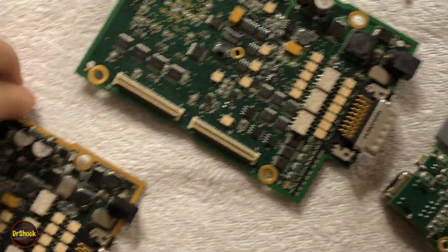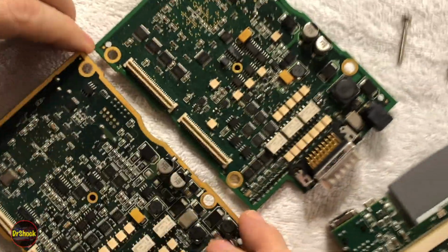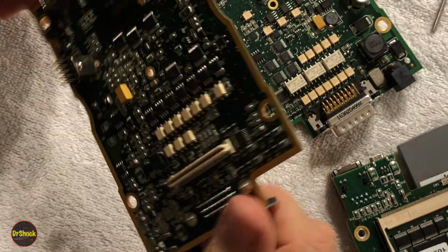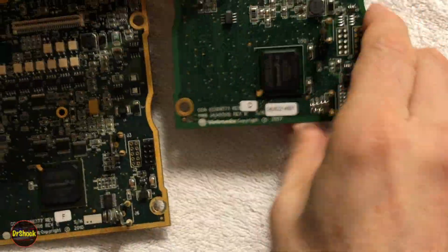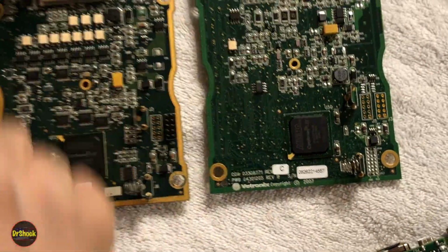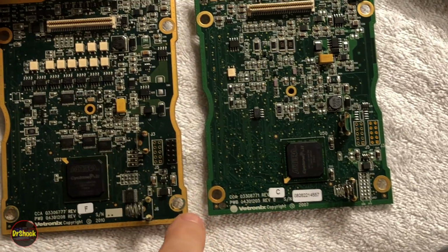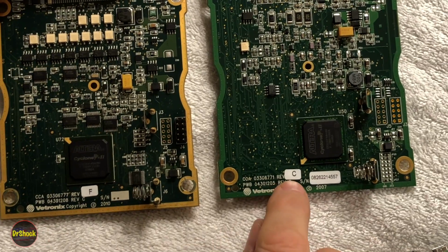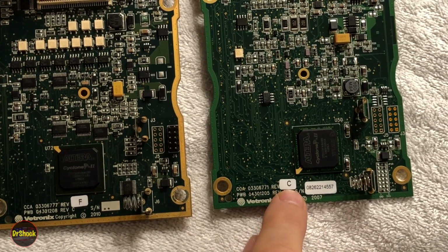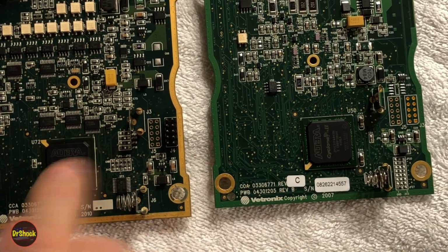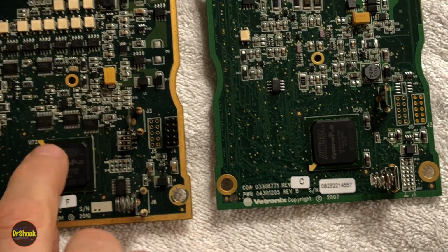So these 2 boards are not identical. So unlike the clones, they went through a lot of different revisions on these with the real manufacturing. I think we can find out by looking here at the bottom. So this one that works has an additional exposed ground plane around the edge with no solder mask on it. And it's a revision F board. And this one that doesn't work is a revision C board. You can see that the orientation of the FPGA has changed, right? Pin 1 position has changed.